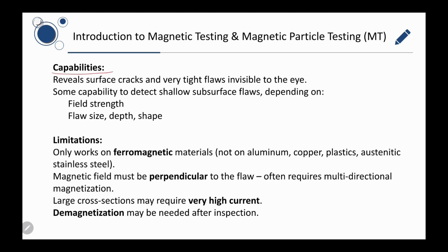Detection of surface cracks: it reveals surface cracks and very tight flaws invisible to the eye. MPT is highly sensitive to surface breaking defects, including cracks, laps, seams.